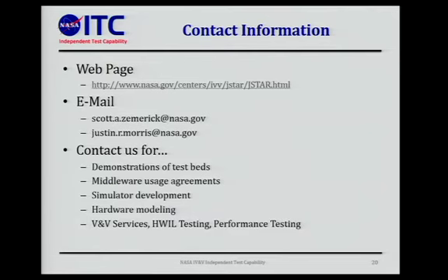Yes, I was more concerned with some sort of hardware which takes some time for a certain action. So you write a register, for instance, and after, let's say, 5 clock cycles, not before, you should read back a result from that hardware.